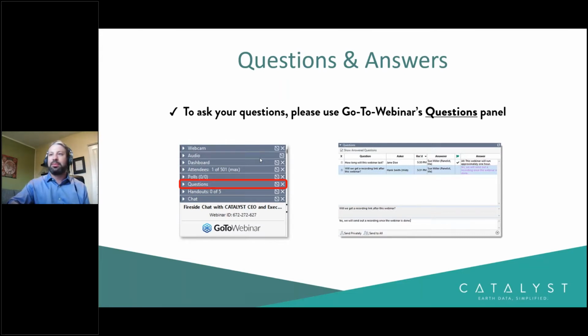Of course. So the analysis-ready data workflow has three main steps that are made up of multiple smaller steps. The first is geometric correction, taking the imagery and aligning it, utilizing our own automated GCP collection and the SuperRegistration techniques, just to ensure that the geometric alignment is correct.